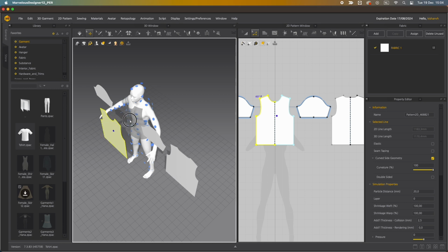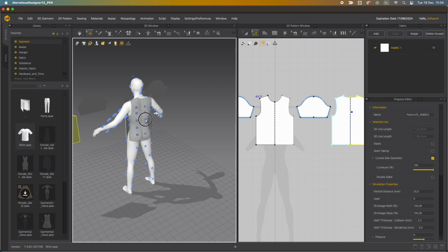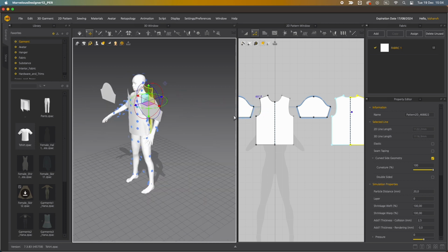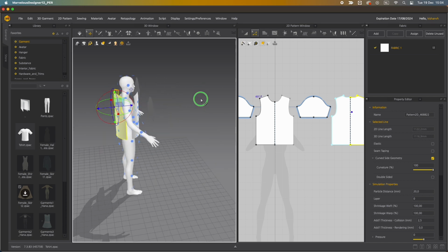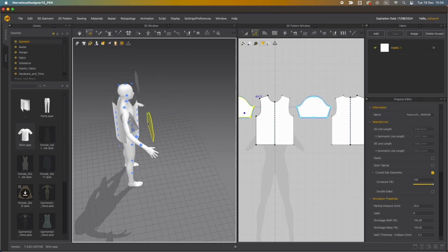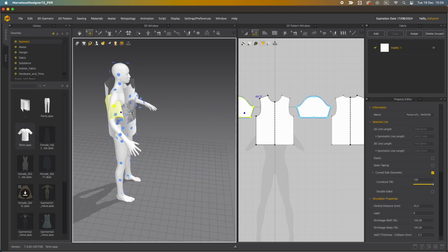Select a shape in the 3D view, then drag and drop it onto the desired arrangement points of the avatar for precise positioning. Repeat this process for all shapes. Ensure the white side of the surface is facing outward. Holding and dragging the green ring allows rotation around the axis of the green arrow. Pressing the Shift key while dragging ensures the surface aligns straight when the rotation is nearly accurate.